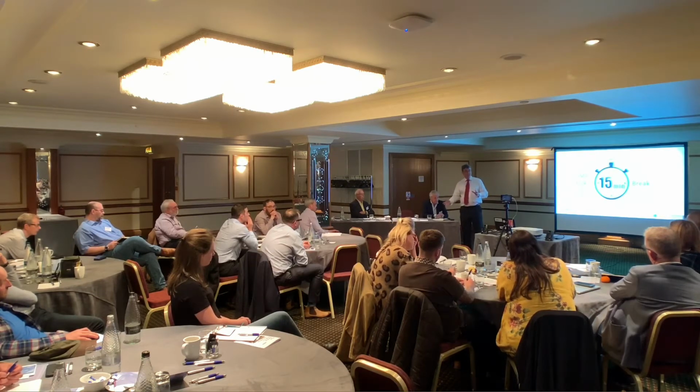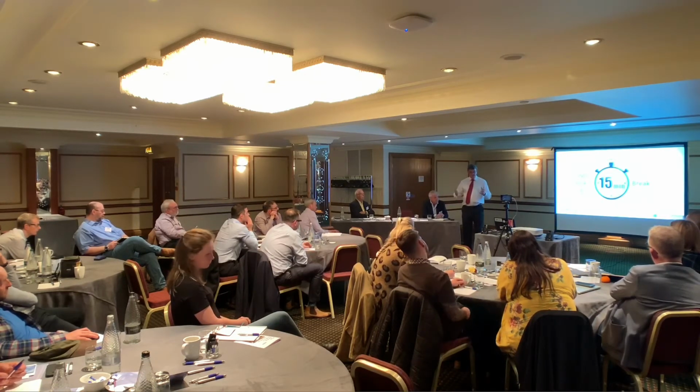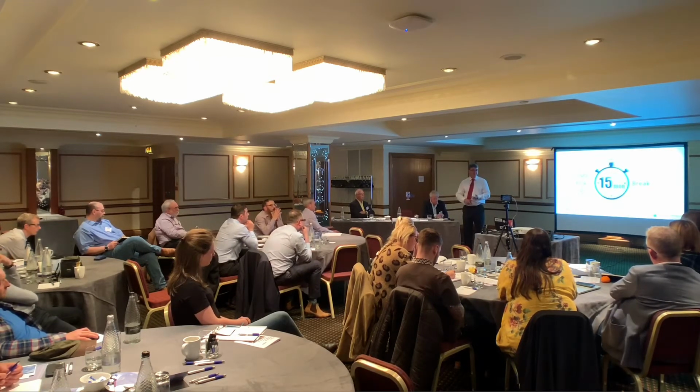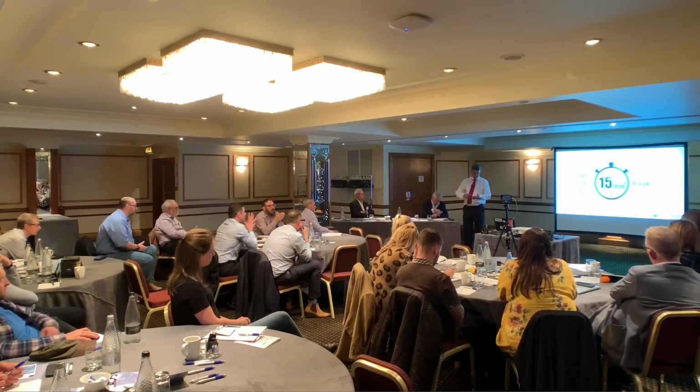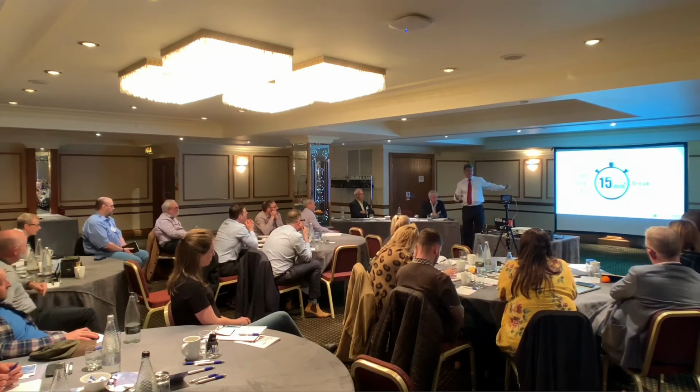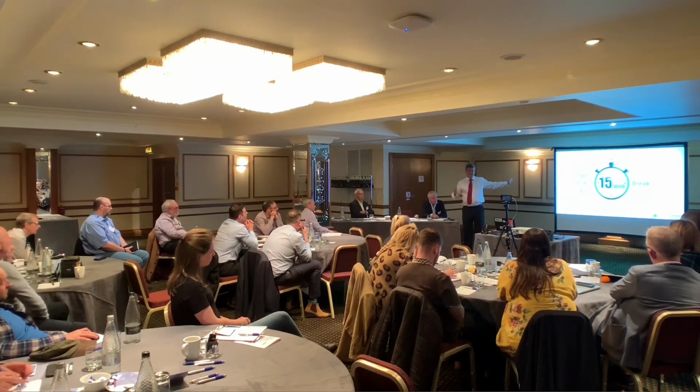They start defeating the reason for going longer and the reason for using a microtunnel rather than a normal tunnel. Now, the difference between a normal tunnel of 2.4 and a microtunnel of 2.4: a quarter of the number of men, a tenth of the settle time, half if not a quarter of the number of men in the yard, quicker, faster, and nobody underground almost. A couple of blokes, that's all you're looking at, and they're in the pit bottom. And the number of times you go into the tunnel is rare. So the economic and commercial reasons for using a microtunnel are just there.